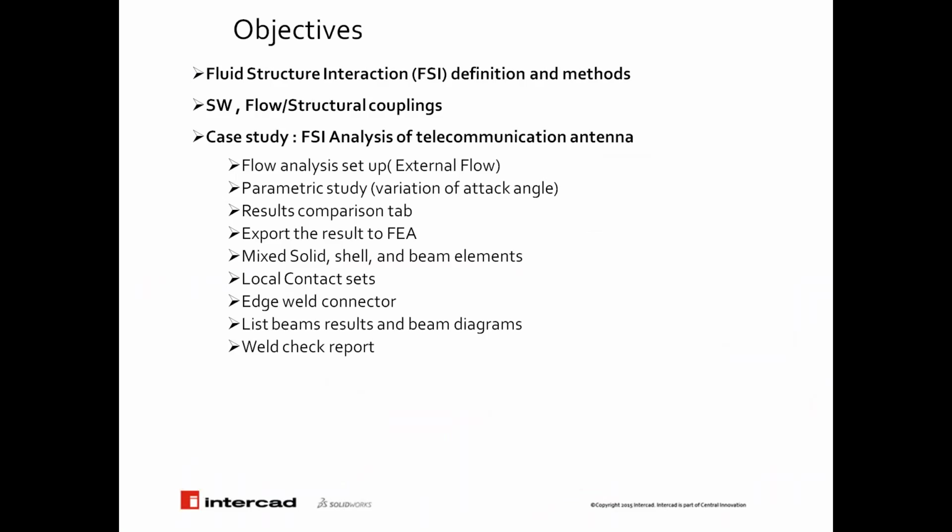And then we are going to focus on the SolidWorks fluid and structural coupling methods we have, and explain what the procedure looks like. We will continue our presentation with a case study. The model of a telecommunication antenna has been selected to do the FSI analysis. In this regard, we first start with the flow analysis setup as an external flow over the object.